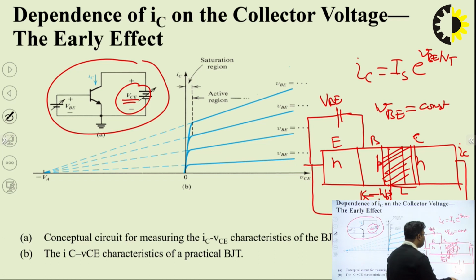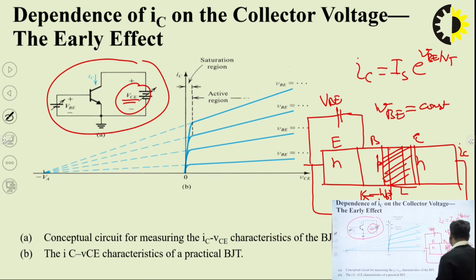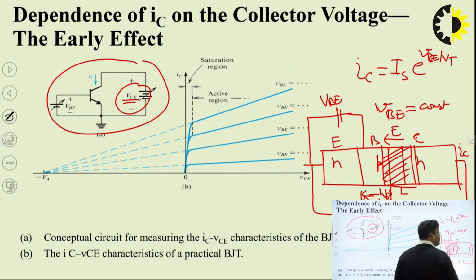What would be the effect on characteristics? The depletion width will be increased, means the space charge region will be increased, and with the increasing space charge region, the electric field, which is due to the availability of immobile ions in this region, will be increased. If the electric field is increased, then the drift phenomena will be more frequent and IS will be increased.